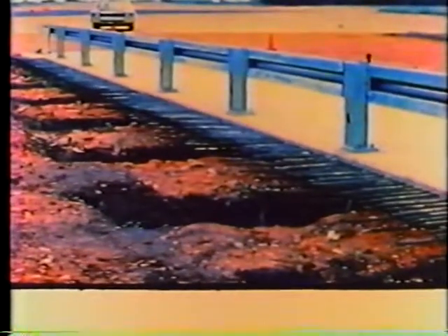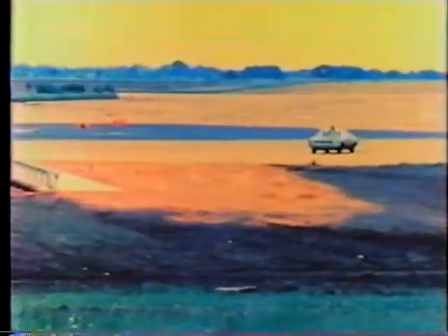This standard bridge rail consists of a W-beam guardrail section backed up by 2 box beams mounted on steel breakaway posts. The tensile continuity of the rail makes the system work. This railing also redirected an intercity bus going at 60 miles per hour, hitting the railing at a 15-degree angle.